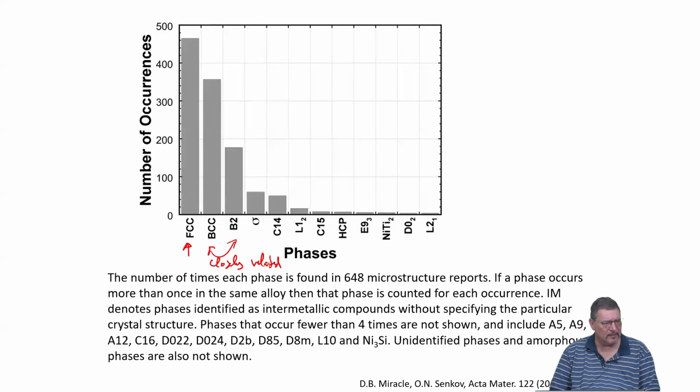The sigma phase obviously occurs often, but you see it occurring often because it will form at the lower temperatures in many of these FCC high entropy materials. And yeah, these more complex structures are very rare, and often they form also as precipitates in given high entropy systems when they are needed at lower temperatures, so that they go from single phase to two phase or more multi-phase structures, especially decoration of grain boundaries, of triple junctions, and so on.